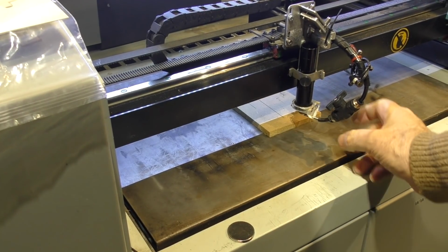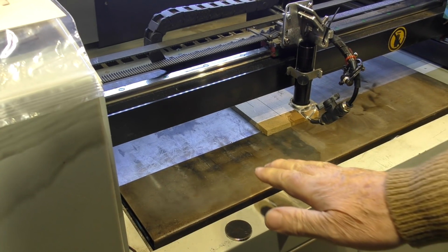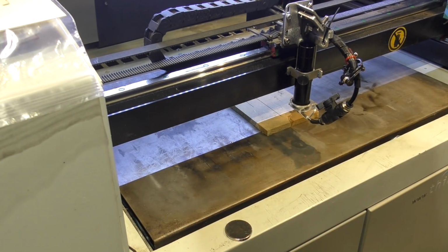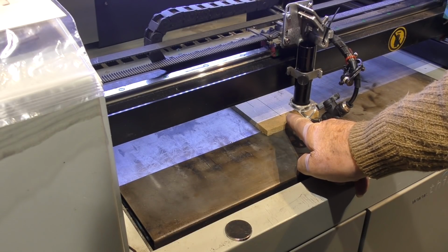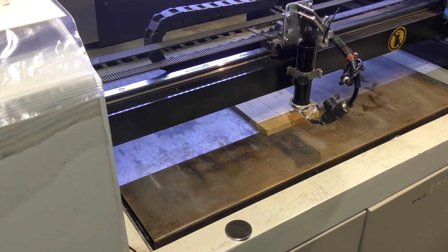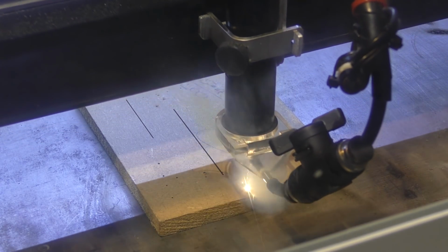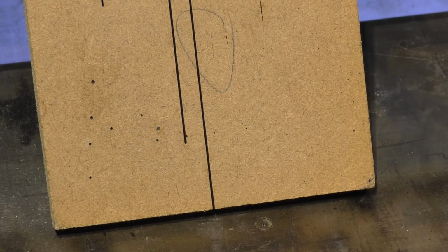And that air, if I just turn it around slightly, is now going to assist my managed airflow, which comes through just here and goes towards the back of the machine, and it's going to drive the smoke backwards, but it's also going to protect the lens without driving any of the air down onto the work. Let's look at the fumes being drawn away with this managed airflow and this different air assist for engraving. Not a hint of browning anywhere.